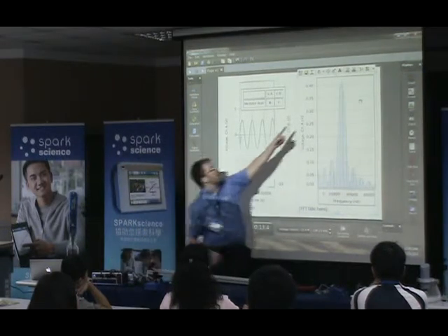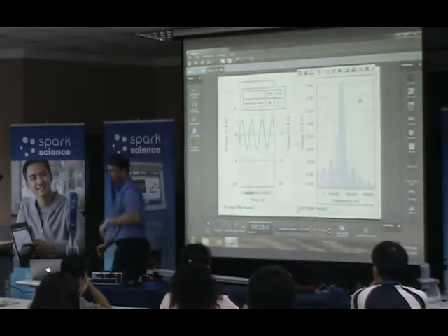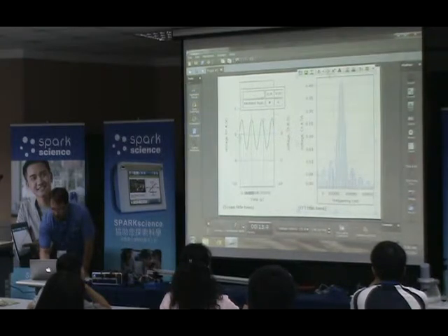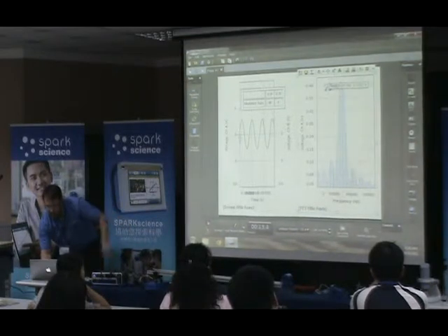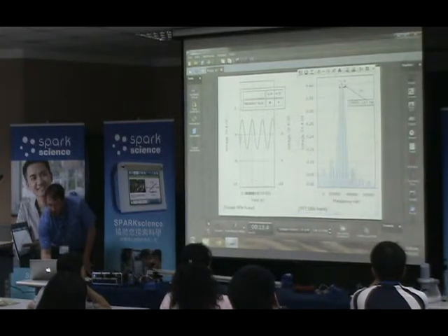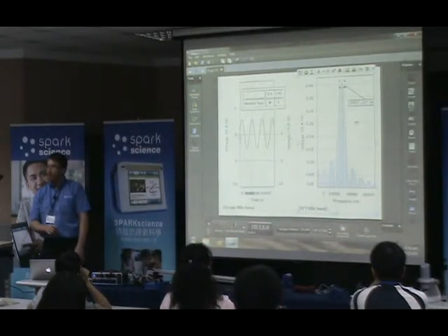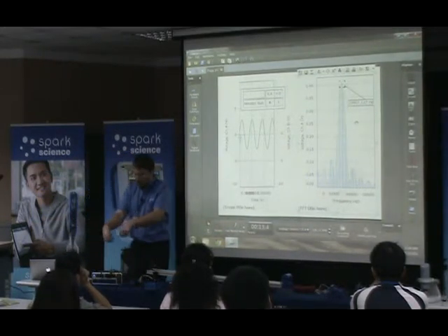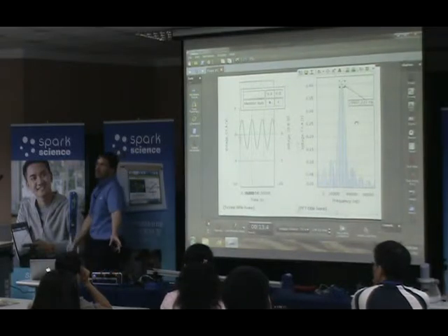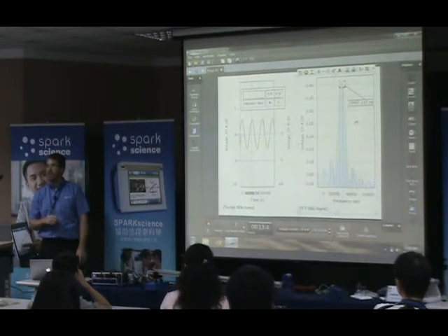So let's say that students want to know, okay, what is that frequency? What is that frequency where I see that real big peak, right? That's probably what the actual frequency is of these waves. Well, I'm going to turn on my tool, and notice my tool kind of snaps to these data points. So I don't have to be exactly on it. I can just let it snap to it. So there's roughly my frequency. All right, 29,000 hertz. So the in-phase frequency should be about that number, and it can analyze it and show it to you like this. And if you actually were to go through and do the calculation with these numbers here, the actual frequency is 30,200 hertz. So I'm very close to arriving at my actual resonant frequency for this circuit.